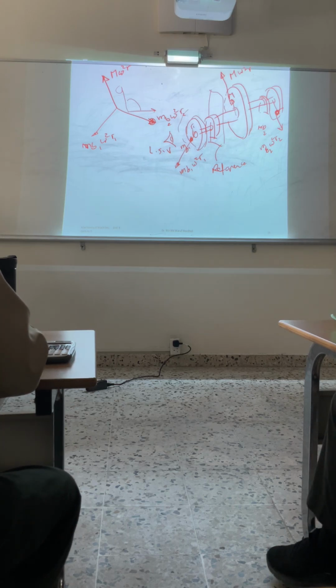But when it comes, listen carefully, to the other balancing condition, which is summation of moments, you have to be careful, guys, because in this case, let's assume that I'm taking a moment around any arbitrary location. Let's assume that this is the reference location for the moment. You got my point? Now, guys, before you proceed and think about summation of moments, either analytically or graphically, you have to see how to calculate the moment for each centrifugal force.